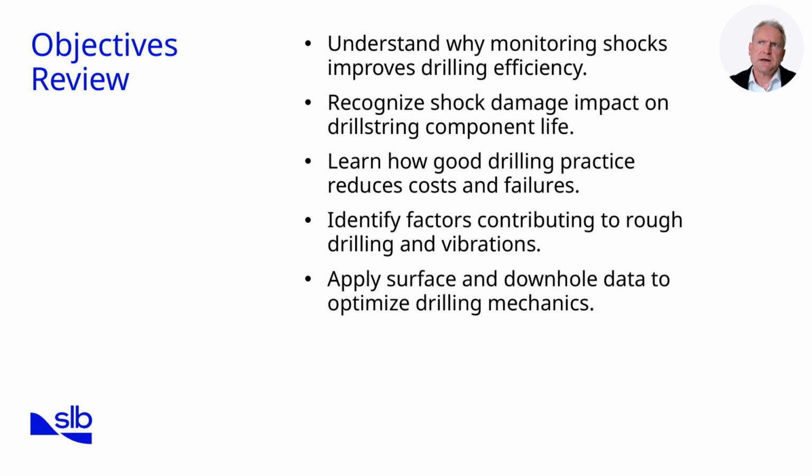From there, we studied drill string dynamic motions, axial, torsional, and lateral, and considered how they are detected through surface and downhole sensors. Finally, we placed all of this within the broader drilling mechanics context, emphasizing that vibration control must be integrated into the overall optimization process.